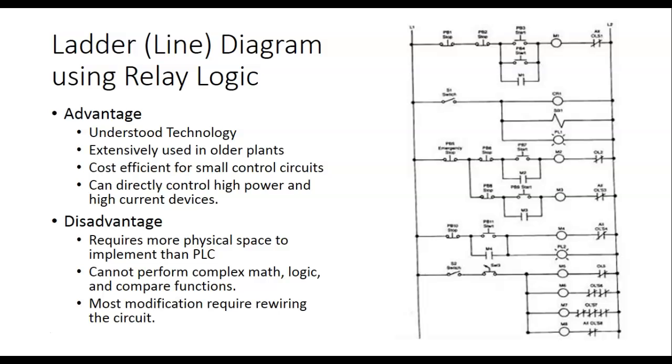And the problem we have is the amount of current we can get out of a PLC is not very much. This is part of the specification on the programmable controllers, it's usually on the magnitude between 1 and 2 amps. But 2 amps would be plenty to bring in a nice size motor starter relay, and then that could run the motor.